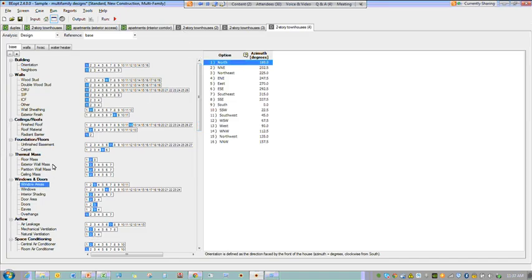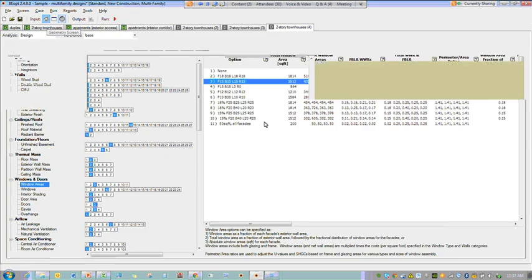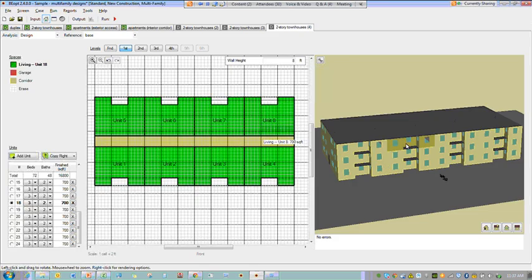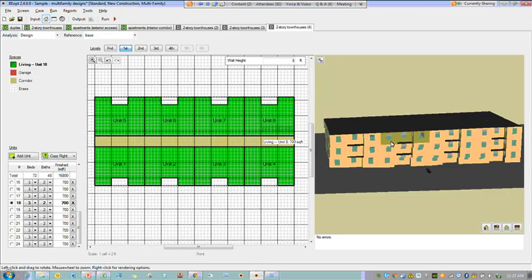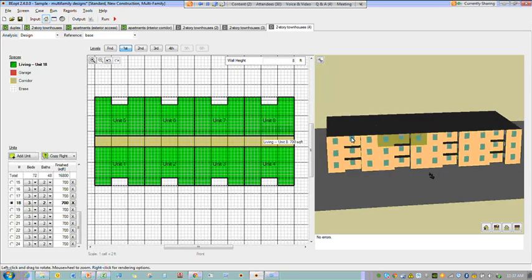The window option that you select will define the square footage of the windows on the 4 facades, front, back, left, right. And the way these total areas for the 4 facades will then get split up to the individual units based on each unit's exposed surface area on that facade. So in general, this works well, and if you have units with equal surface area on a given facade, then it'll distribute the windows equally.